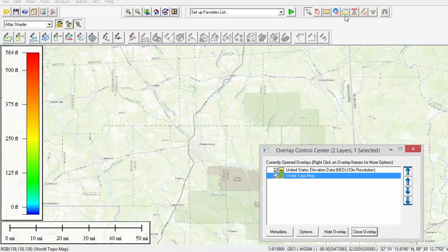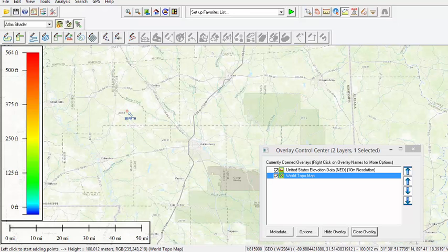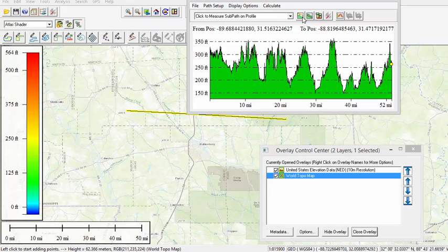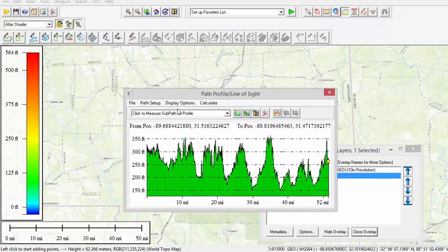And now when we go into our line of sight 3D path, click on here, let's hit a couple rivers over and see what that looks like. The moment that I right click on this guy, it's going to go out and process that line of sight from a three-dimensional elevation and use the forward-facing raster image of the topo map and pull from the data in the background image with the DEM. And here it is right here. So you've got your profile line of sight.